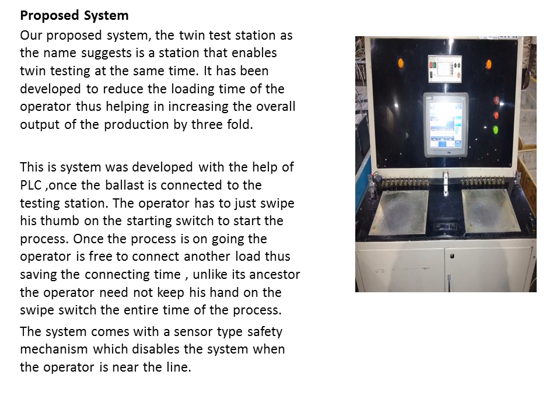Once the ballast is connected to the testing station, the operator just has to swipe his thumb on the starting switch to start the process. Once the process is ongoing, the operator is free to connect another load, thus saving connecting time. Unlike its ancestor, the operator need not keep his hand on the switch the entire time. The switch comes with a sensor-type safety mechanism which disables the system when the operator is near the line.